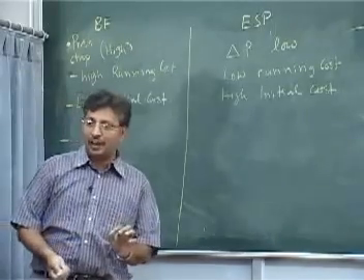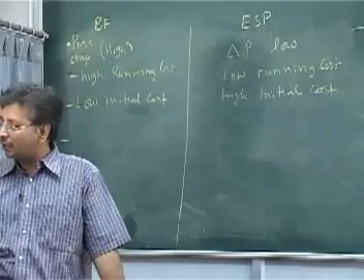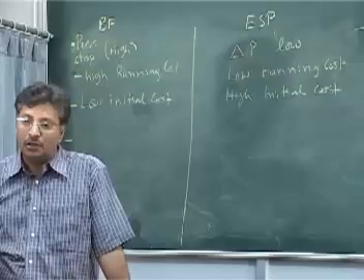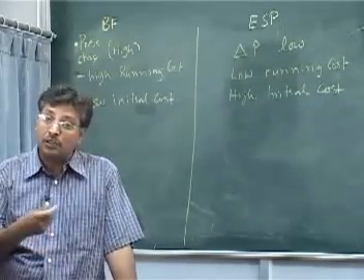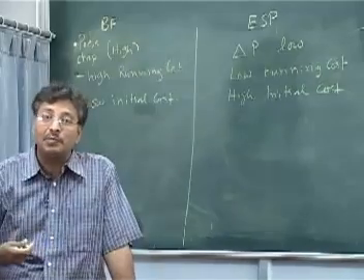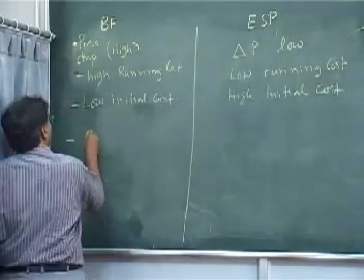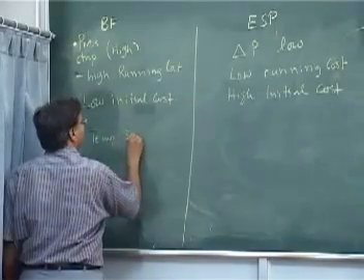Given the type of the bag and the temperature, can all bags or fabrics resist all temperatures? No. If cotton is there, for example, and the heat is very high, it may not be able to resist that. So the bag filter is temperature sensitive.